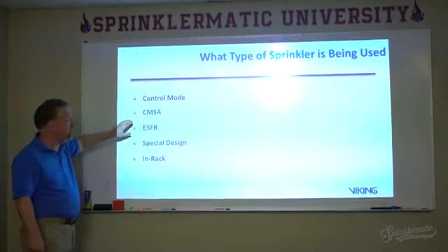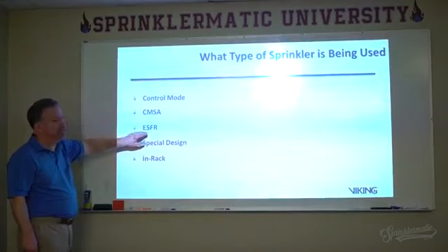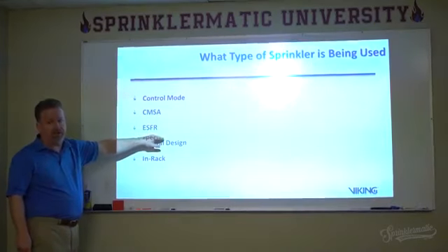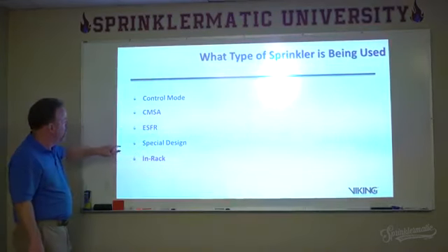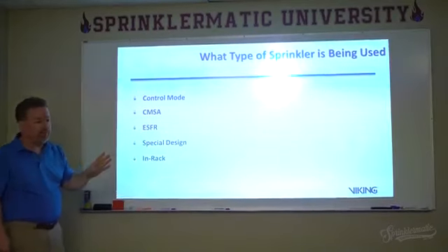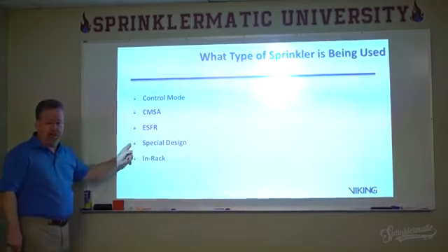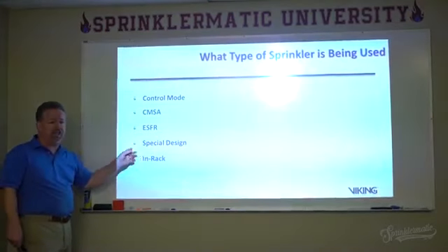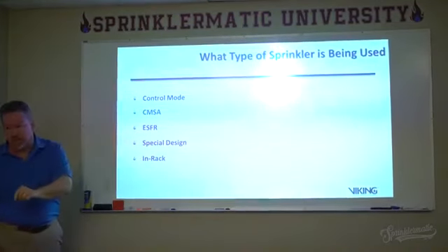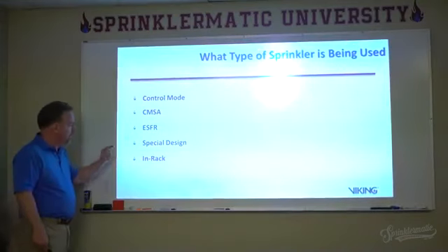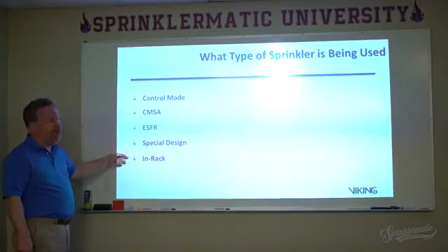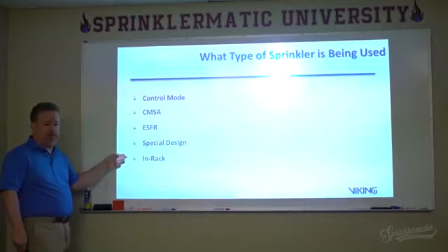Are we going to use an ESFR sprinkler, which is an early suppression fast response sprinkler? Or are we going to use a special design? Maybe there's a special type of sprinkler or a special design arrangement that is specifically geared towards protecting this commodity in this arrangement. Or do we have to use in-rack sprinklers?